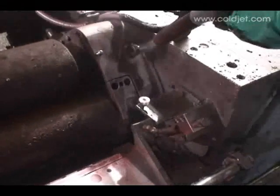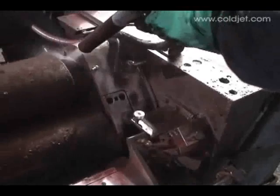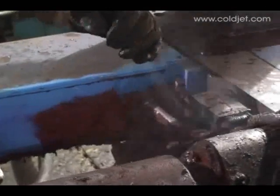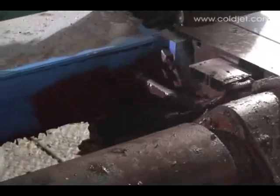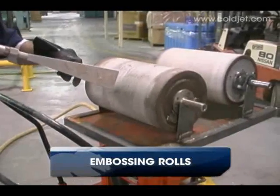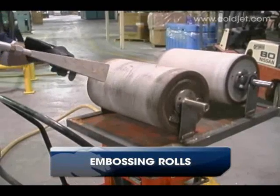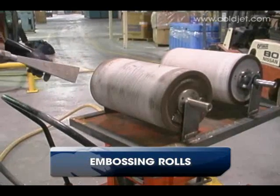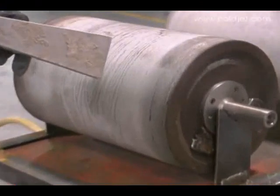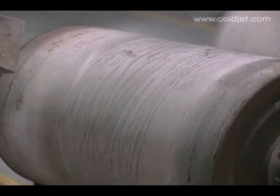We were actually looking for ways to clean them. We were kind of at a dead end. We didn't have any alternatives or any solutions to getting that buildup off. We had to have something that would take the buildup off but leave the ceramic coating on, and that's exactly what the dry ice does. It takes the buildup right off, and we don't lose any of the texture on our embossing pattern, and it just does a wonderful job.